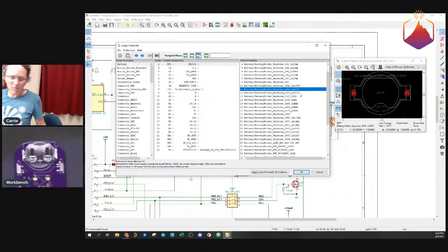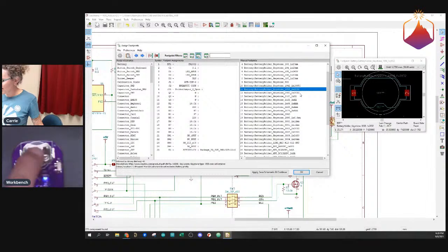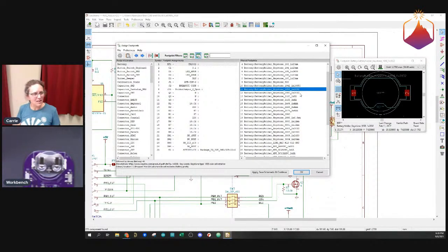The battery just slides in from the front and it solders down on pads. Now, the weird thing is that it's nickel plated, and it's probably stamped brass that's then nickel plated. The nickel plating means you can actually solder to it, and it won't tarnish or oxidize if it's just sitting out.